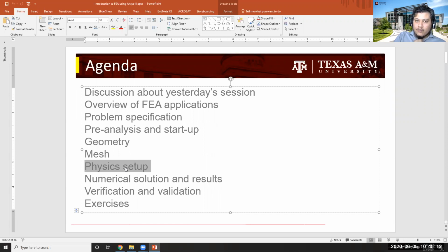At that scale, I have to be pretty cautious about the anisotropic elastic as well as anisotropic plastic properties. What is the slip behavior in the titanium alloy? Are the conditions allowing twinning to happen? How is the behavior at the grain interfaces? All these things become a very important aspect, okay?